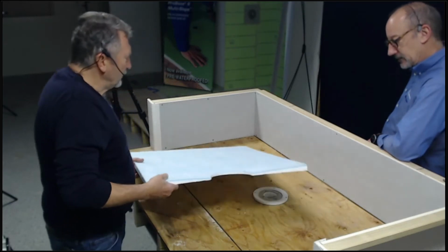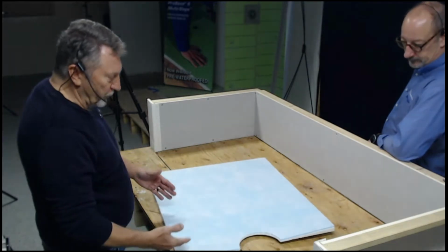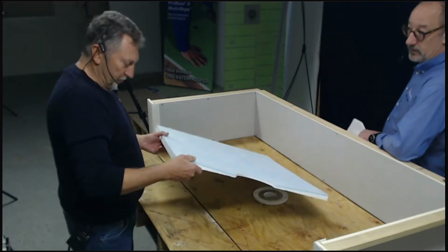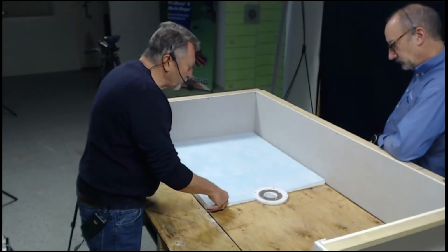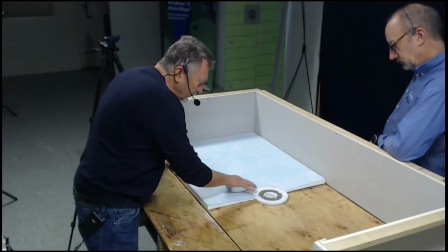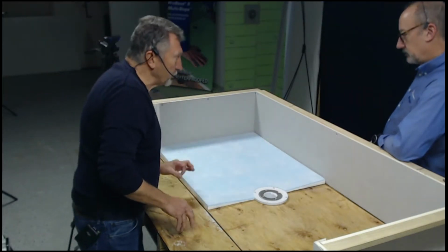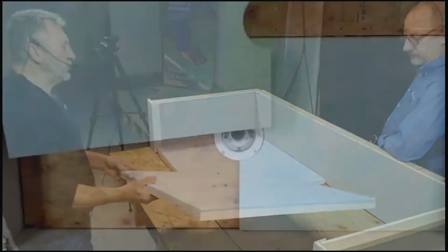It's very easy to install. You simply use a straight edge and a knife, you cut it, snap it, just like you would backerboard. First of all, we're going to pre-measure and pre-cut, dry fit it, make sure that it lines up with the drain properly, and we've got a little bit of gap around our perimeter. Don't want it too tight. Expansion, contraction. Now this 3260 comes in 2 pieces.